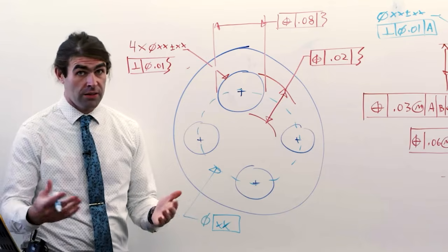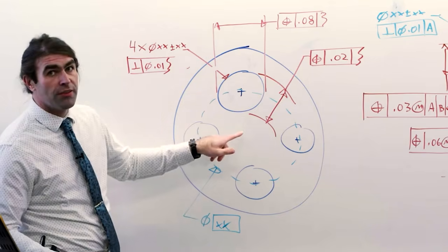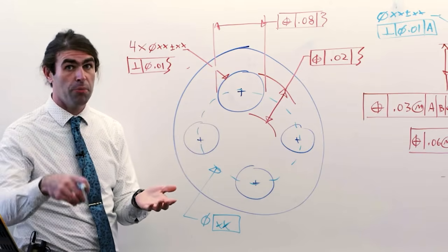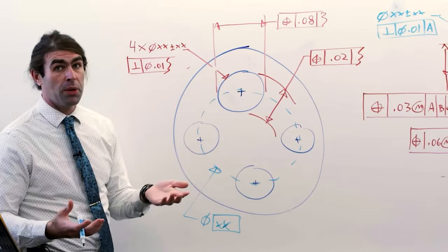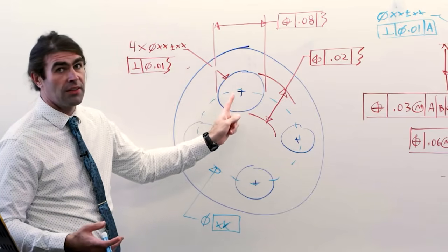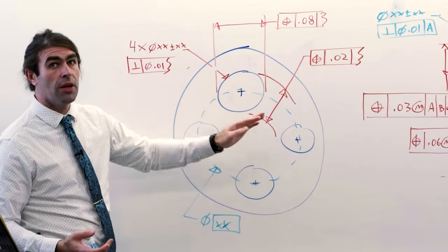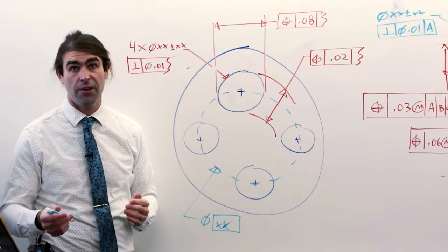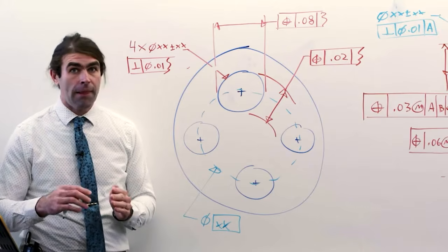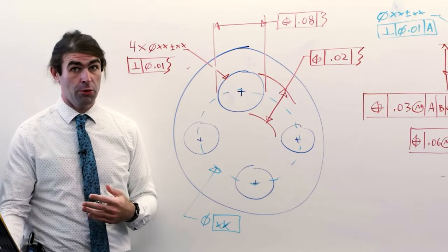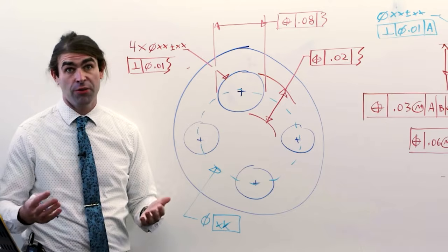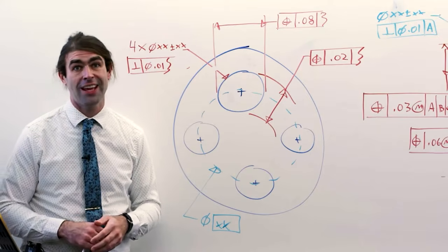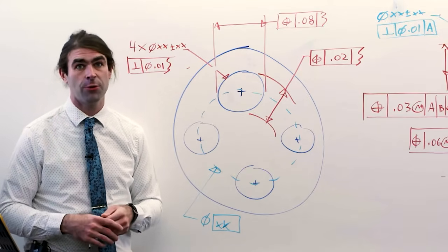One use for this that I can think of is, say, this plate fits below a plate with slotted holes, right? So when you're fitting a bolt through, it might not matter as much whether this is in tolerance in this direction, but it does matter in this direction, depending on how the slots are toleranced. Now, like I said in the beginning, this isn't stuff you necessarily need to use, but it is there. And if you want to get deeper into GD&T, this is good stuff to know, especially if you want to take the certification exam. This is the kind of stuff they like to throw on there.